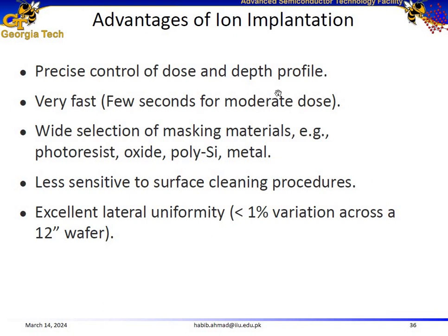So for this purpose, ion implantation achieves precise control of dose and depth. It is fast as well, does not take a lot of time. We have a wide selection of masking materials, for example, photoresist, oxide, polysilicon, etc. It is less sensitive to surface cleaning procedures.